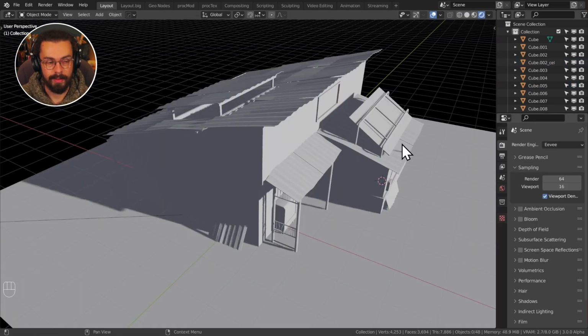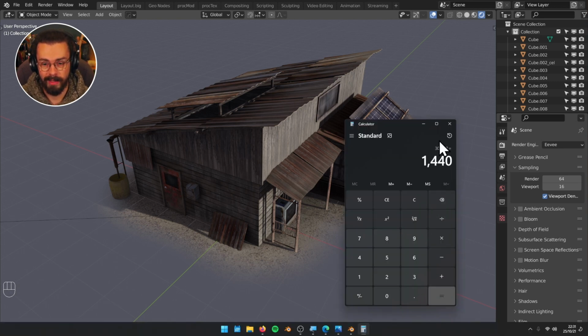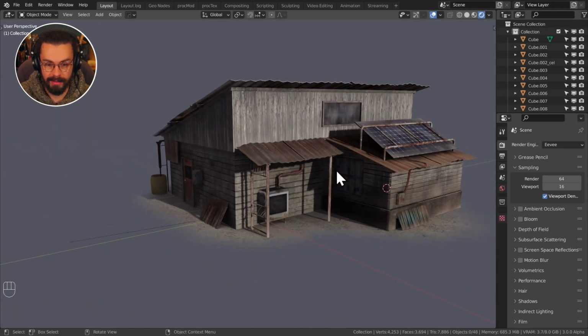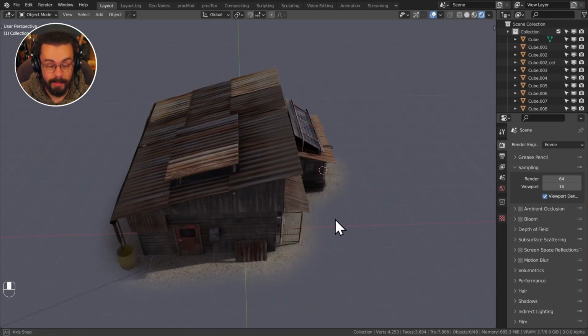If you think about how long it takes to render in Cycles, multiply that by 48 for your minimum Quilt render. So if you render an animation that has 30 frames and each render takes 48 renders to complete the 3D view, then suddenly you're looking at an awful lot of time spent rendering. At a minimum it's 1440. So it's a lot of renders it's going to do. You've got to be cognizant of that when you're making renders, and this is why I'm going to be doing this on EEVEE. But this model still looks great.